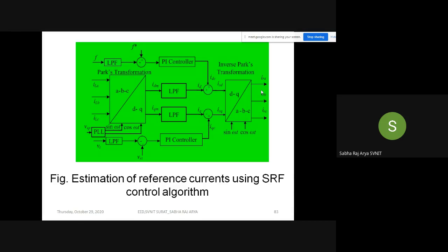Okay. So now the point is, what is the requirement of this LPF filter? Because we want to reduce the oscillating component. We want to block the oscillating component. For that, they have used this. Then how we can do the PI controller? Already I have told you, you can compare and generate that VT equal to VRT. If both are equal, then in that condition we are going to get a minimum constant PI output, a constant DC. After that you can do whatever you want.